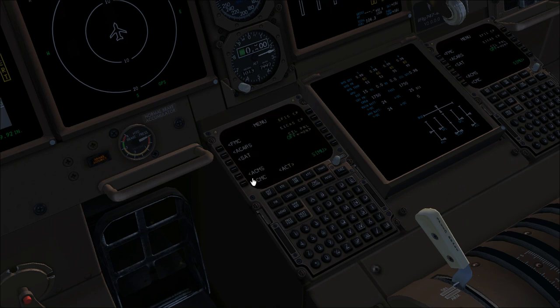Anyway, coming back to the menu, we can go to the FMC. You can see the ident page selected, and we are in the ident page. In the ident page, you have to check that the model is correct, the engines are correct, the navigation database is correct, and the cycle data is 1410. We are in November, but that's not a problem for now. The drag and fuel flow indicator coefficients are 0, and the op program is 2.